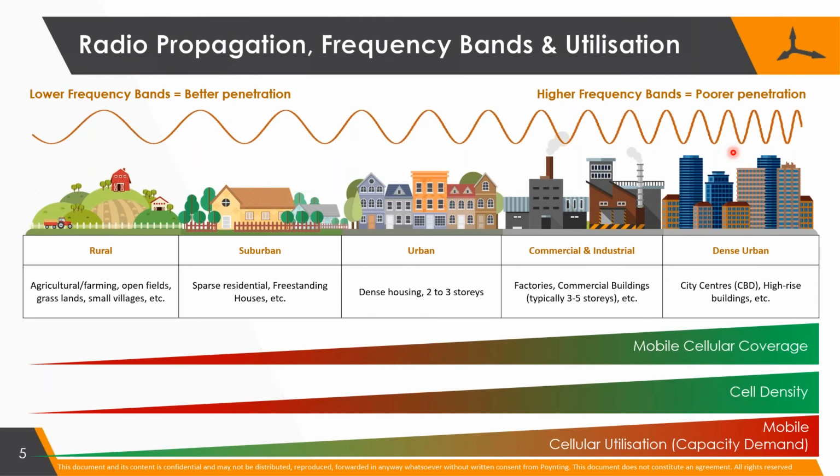The first part is really the basics of propagation. If you look at this here, this is indicating a low frequency. Typically, if you talk about the cellular bands, this would be around 900, 800, 700 megahertz. You can see that the frequencies will increase on this side. Now, if you look at the scenarios, we typically find that people use these low frequencies in rural types of environments. The reason for that is quite interesting, in the sense that these frequencies penetrate bushes and vegetation, and they also give you longer distances.